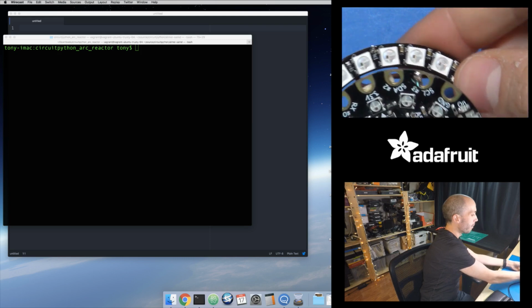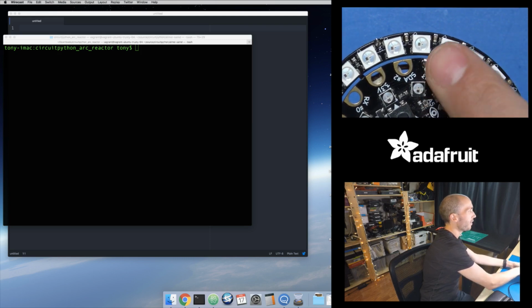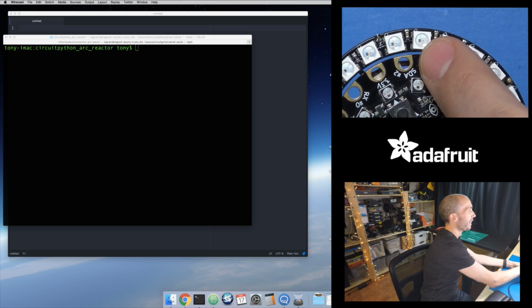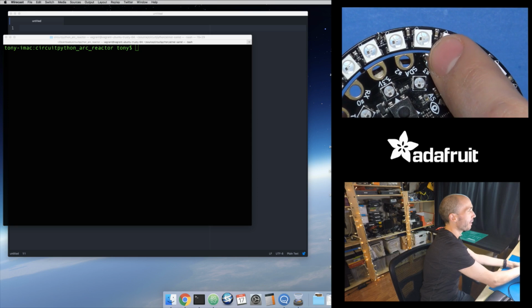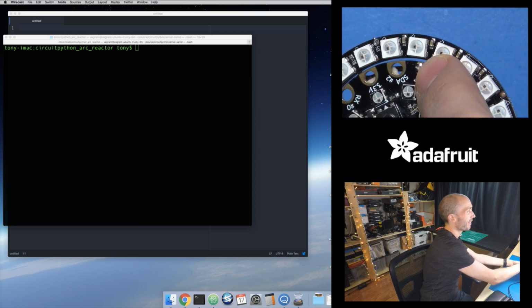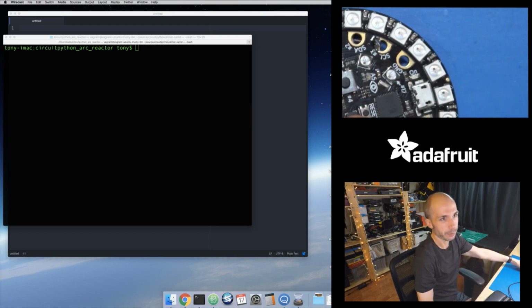That's because, again, remember that clearance. So when this comes down, notice how you've just got a fraction of an inch right there. And if I had that wire sticking out, it might hit that NeoPixel, or it could touch some of the contacts. You see there's the NeoPixel contact on the side there. That could short that out. That would be bad. So be careful, and you kind of need to think it through.